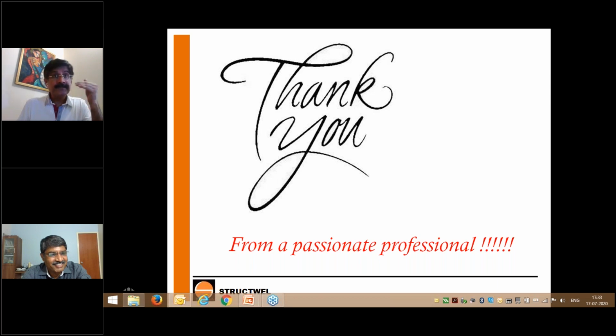And sometimes the client really does not have the budget, really does not have the money. So that is where you don't try to put the wrong material. You leave it at that and say, sir, I am leaving it at this much. We will do it later when you have some funds for doing this. It is better not to do a job of conservation than doing a wrong conservation. Structural conservation must be done, and you can really bring the cost down substantially in doing structural conservation. Architectural conservation is expensive, but it's not a necessity for the structure to live. Somebody can do it 5 years down the line when the client has money. This would be my answer to the question.